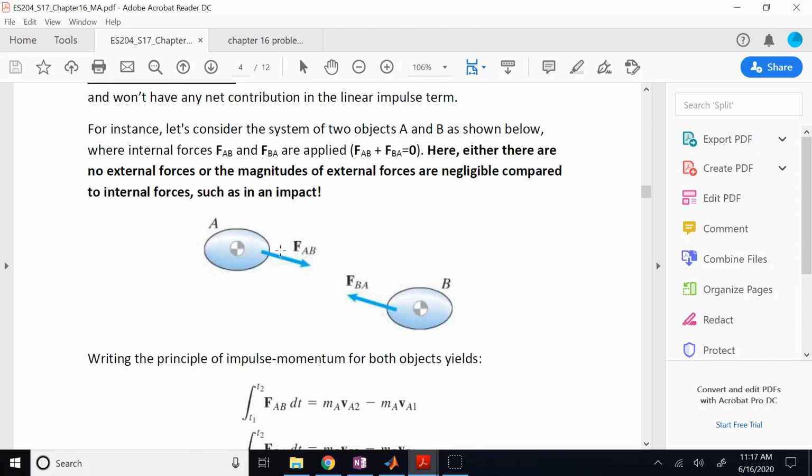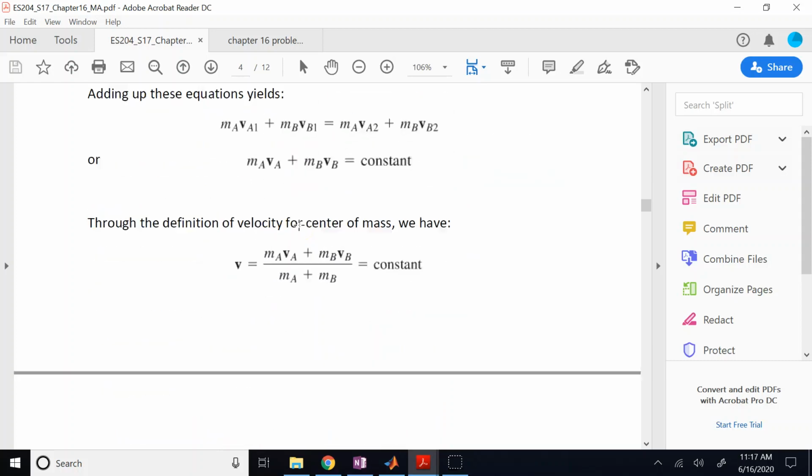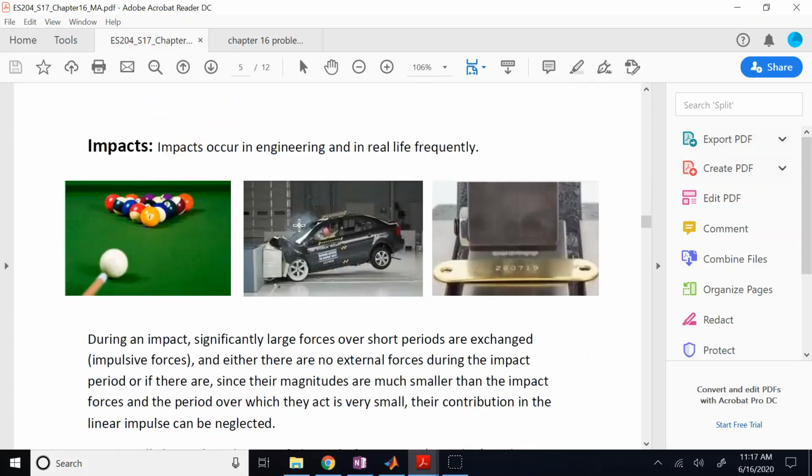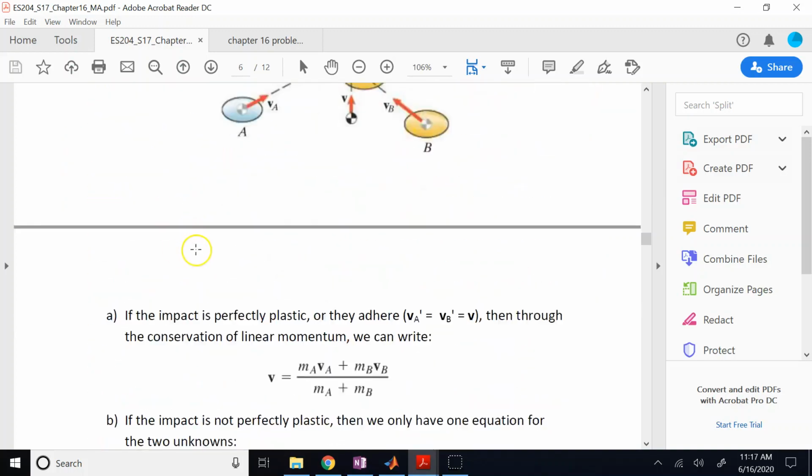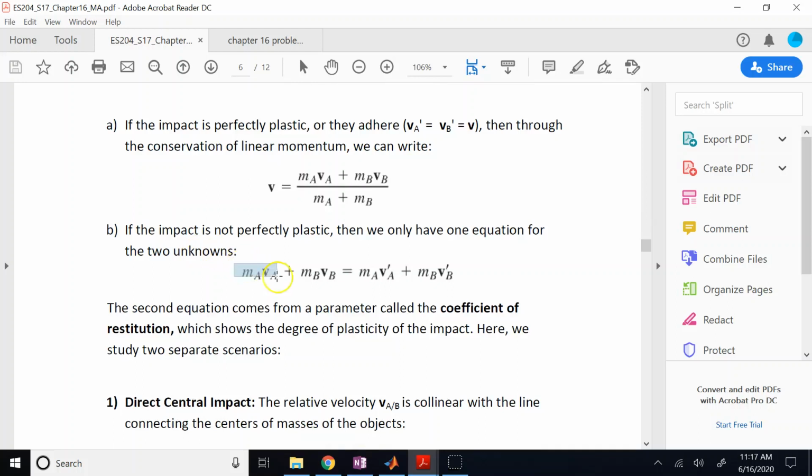If the masses are huge though, and the application is super accurate, we cannot really let go of anything, then we cannot use this. So it depends on the application, but again, for many routine applications we use on a daily basis, yes, we are going to use the fact that even if there is an external force, which typically is only gravity, at that short time period that still exists, we neglect them. And so if we do, then now we have our first formula for solving an impact problem.